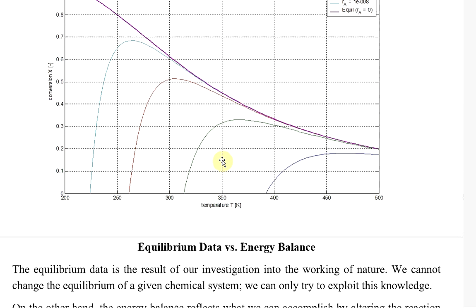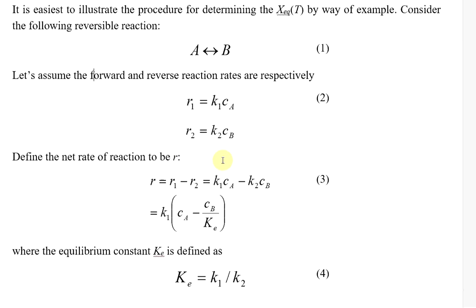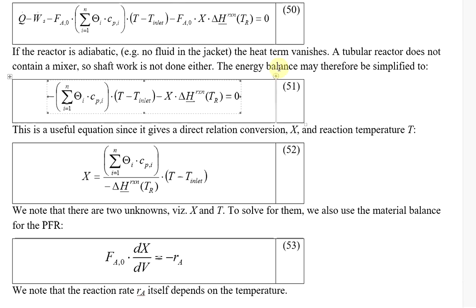And now we want to come in with our reactor design. Let's just go back to our previous development, to this relationship. We said in this relationship, this was the heat added, and that's the shaft work, and then this is the interplay between the conversion of our components, and so the internal energy and the thermal energy given off. This is really where the reaction is operating.